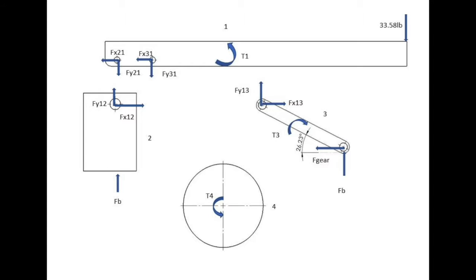We needed this torque to overcome the weight of the tabletop as well as the weight of the sliders. Some of the assumptions we made for this analysis were that there was no friction between the joints. To calculate the moment of inertia, links are assumed to be thin rods spinning on one end. The weight of the table is evenly distributed among the 4 legs, and we chose to ignore the weight of the mechanism links since their weight is so small compared to the rest of the assembly.